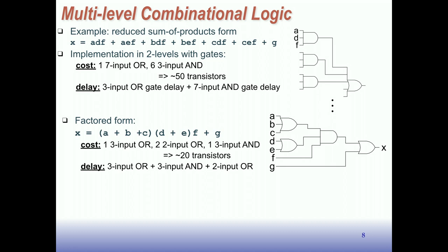And it's because we went to an extra level of logic, there's some redundancy here effectively that you're able to factor out, right? And factoring is the common technique used to generate multi-level logic from 2-level logic. It's one of the heuristics that the tools use in order to simplify your logic. It looks for places to do factoring.